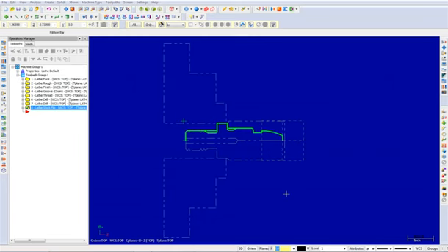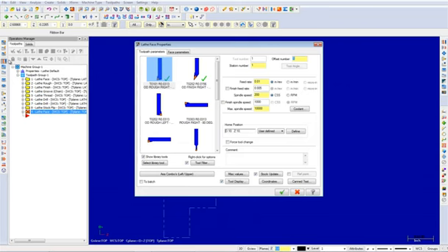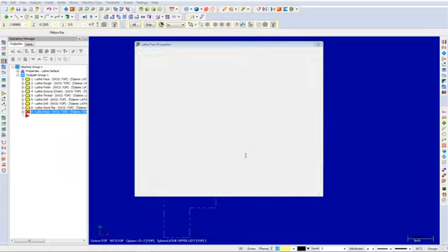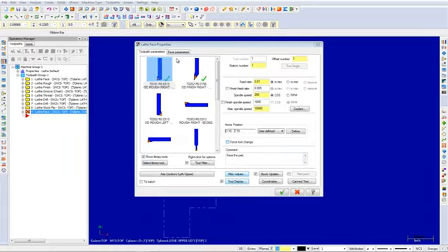The next toolpath we will create on the part is a facing toolpath. Select the facing icon. Select the OD Rough Right 80-degree tool and input the comment Face the part. Now pick the Face Parameters tab.